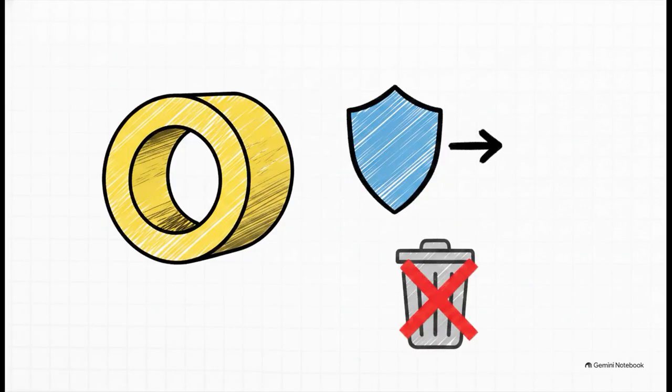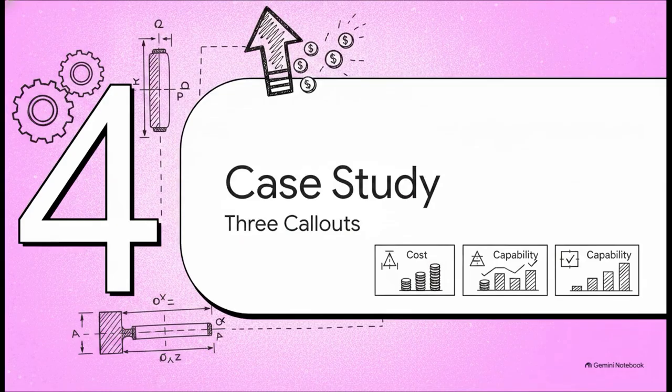And the exact same cost-saving logic applies to LMC under Section 5.9.6. It grants additional geometric tolerance as a feature departs from the least material condition. This is incredibly useful for things like preserving wall thickness on castings. It keeps the part completely functional while minimizing scrapped parts, which directly pulls you out of that exponential cost danger zone we saw earlier.